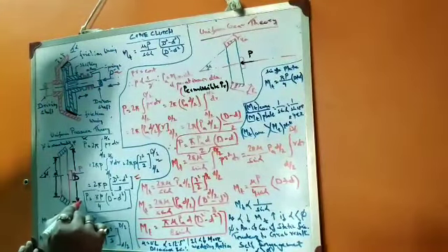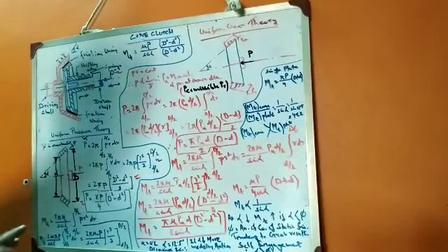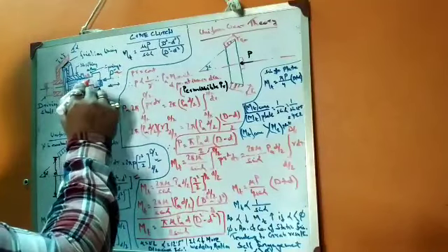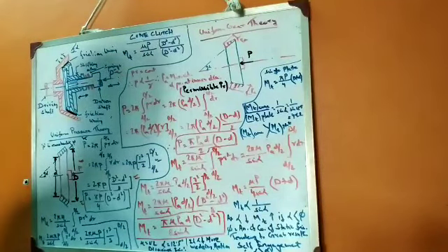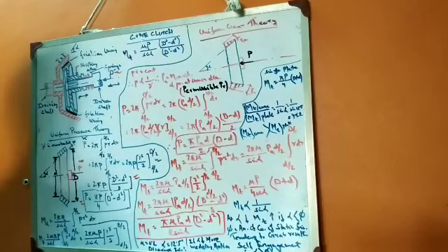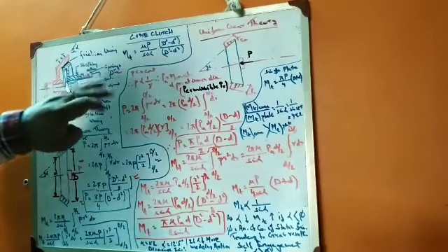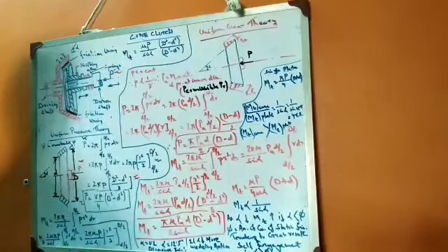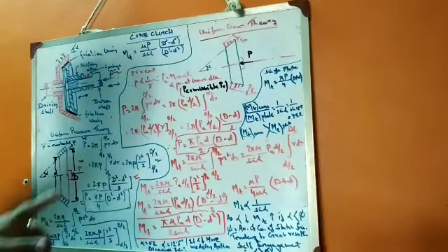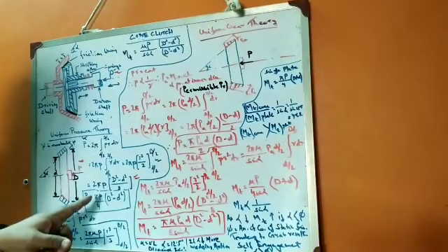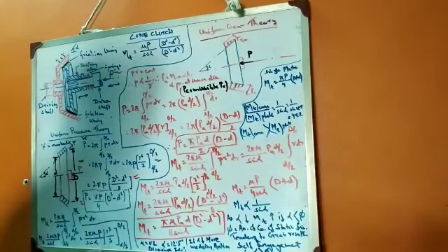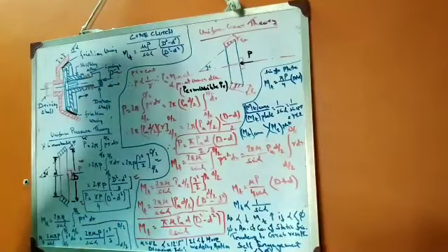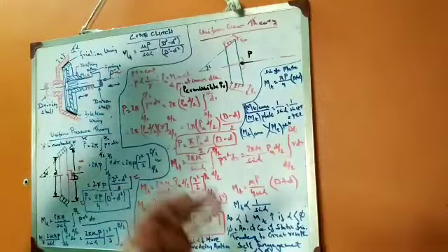This is the applied force that has to be given either by the driver or by any means to the driving side, so that the inner cone of the clutch comes in contact with the outer cone of the clutch. So this is the expression for P, where small p is the uniform pressure, with capital D and small d. This is the actual force required when we are considering a new clutch.